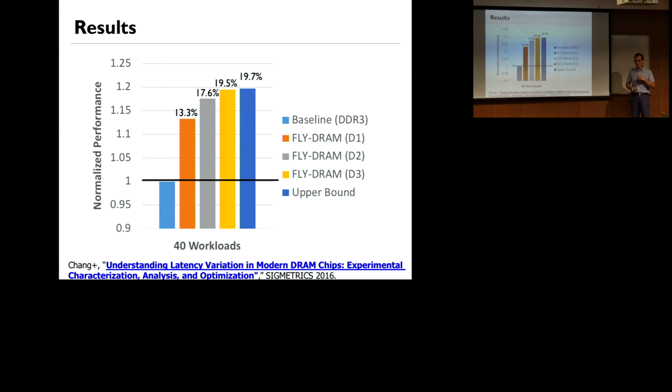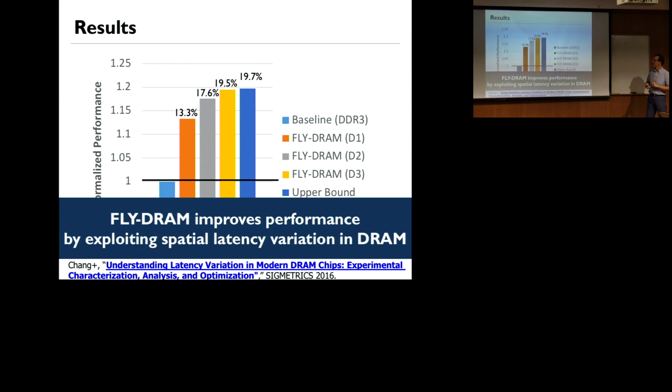Yeah, but it also has to be an SRAM lookup. Otherwise, you have double latency. Yeah, but I think that lookup can be overlapped with many other things that go on in the memory controller. Again, it's not latency if someone is waiting. If you're queued anyhow, the latency of the actual lookup is not the major thing. That's right, exactly.